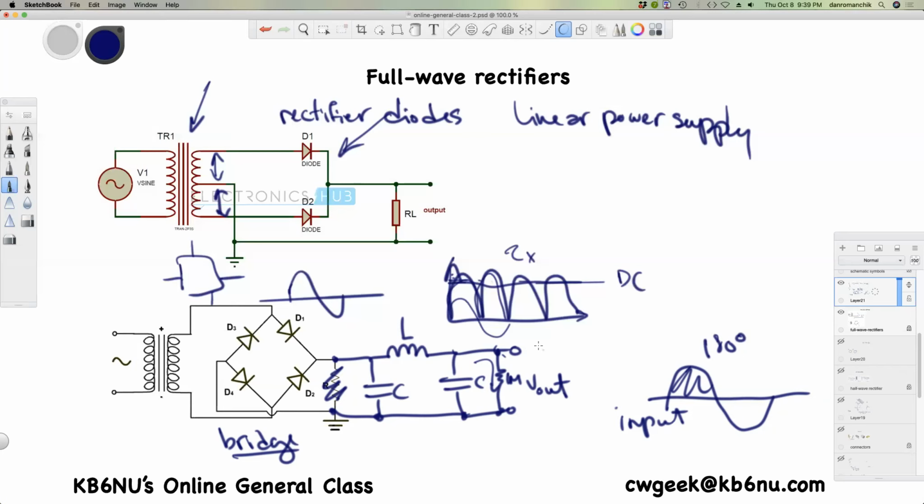When you turn the radio off, no current's going to flow out here, right? These capacitors would be charged up. And if you had a big resistor here, it would have little effect on the output voltage, but then would discharge these capacitors. And that's why you do that. Sometimes this is called a bleeder resistor.